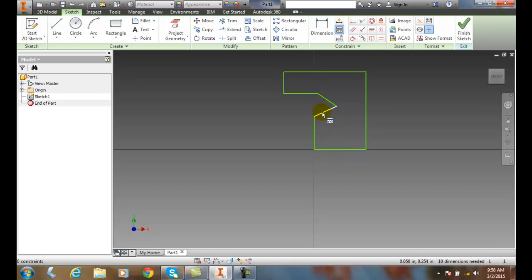And when we get to the skewed lines, you can just see that the coincident ones are shown in yellow. So we can kind of hover over that and we get a yellow coincidence on those little square grips to that. So we can hit escape. So that's just to show whatever constraints are on a particular entity.